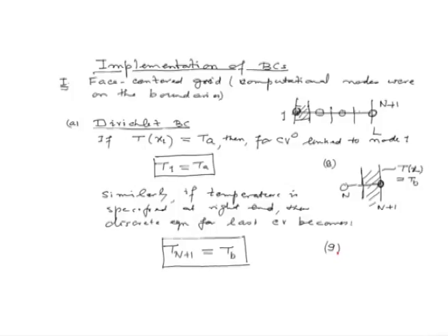Okay. So, in this scenario these are the equations which ought to be put in for the control volumes, and note down that these control volumes are of half width delta x by 2. So, for these control volumes which are adjacent to a boundary computational node, in the case of Dirichlet BC we have got a very simple expression, and these two equations can be put together with the discrete equation for other control volumes to obtain our final system and solve it.